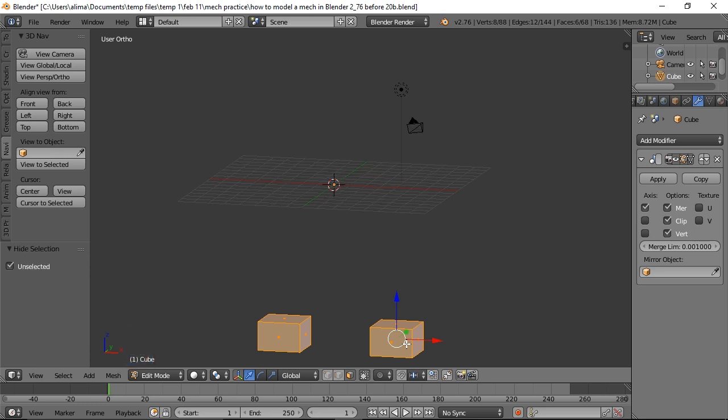Now this is useful in that the reason why this other geometry disappeared is because it is presently hidden. So it's still there, but it's hidden. So it just allows us to focus on what we're doing right here. Also, since I want to just focus right now on this, these are our modifier options right now. If I select this eye right here, we will not see this modifier, which is the mirror modifier, working. So I'm going to temporarily unselect that eye so we can just put our attention and focus right on this piece of geometry right here.